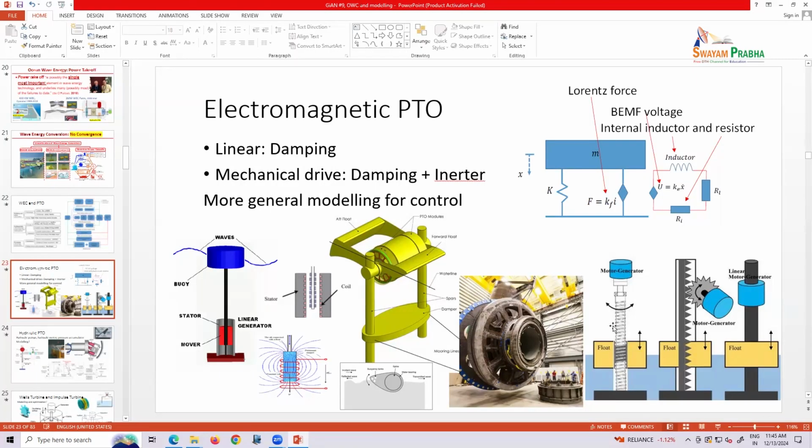The ball screw has a lead angle, right? If the lead angle is large, the motion transmission would be small. Basically, you move up and down, and the generator rotates at lower speed, right? However, if your lead is too small, the generator speed is high, but the ball screw's transmission efficiency is not good, right? Sometimes you may find, wow, I need to use a larger lead ball screw, and I put in another gearbox, 1, 2, 3, whatever. Certainly efficiency will be better, right?